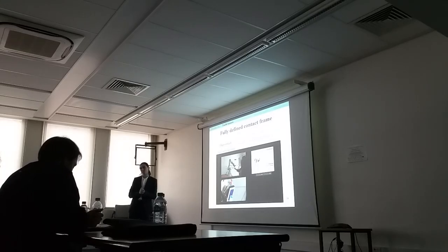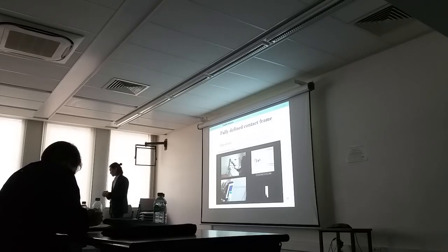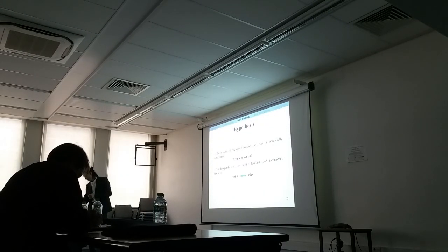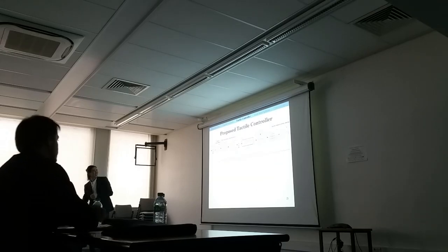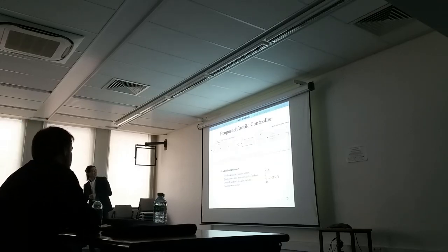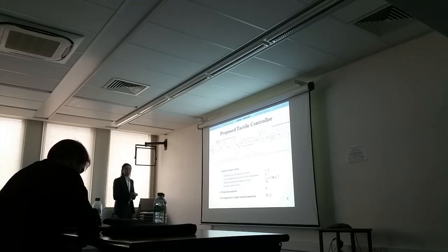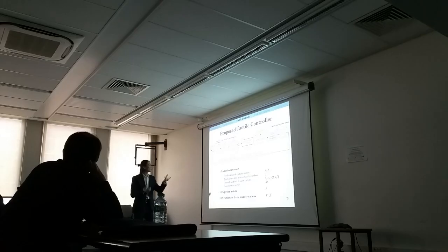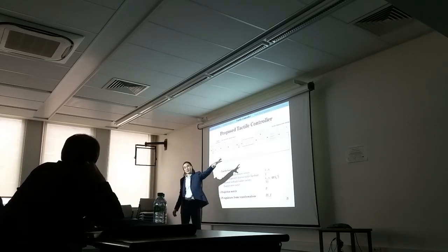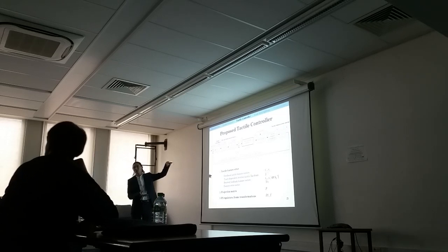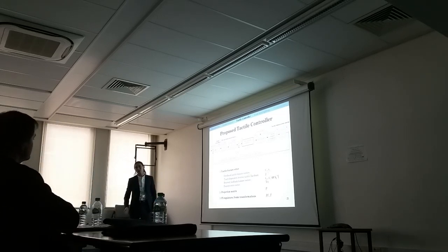Okay. Yes, I have another question about control. You called it a Jacobian, yeah, not this one. Yes, this one is okay. In the tactile servoing, together, the projection matrix with the inverted Jacobian matrix is mapping the feature error to the contact frame errors. That's why it's called tactile Jacobian, because errors are mapped to errors.